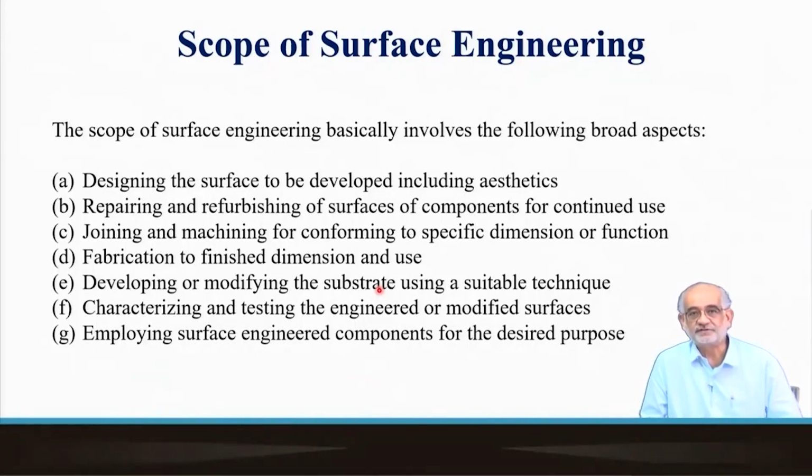Right now I was saying that when you develop millimeters, even 10 centimeter, then you are building a layer so that the component can be used. Maybe a part of a roll has chipped off. Would you like to throw it away, which is not only several tons, but costs several crores of rupees? So you would certainly like to reuse it. There you use a weld overlay and then do grinding and make the surface conform to the exact curvature, dimension and thickness, and still continue to use it.